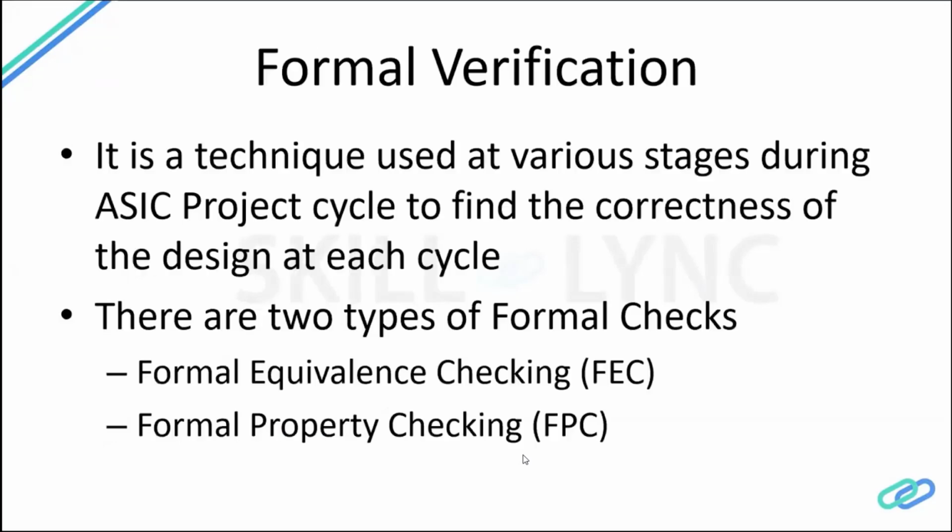Before I jump into synthesis, I'll just give a brief overview of formal verification. Then we'll go back to synthesis after a few slides. Formal verification is a technique used at various stages, wherein we check the RTL against the netlist. Whatever netlist is generated after the synthesis, we compare that netlist with the RTL which we have written. Why is this check needed? We have done a design, and we give constraints while generating the synthesis.